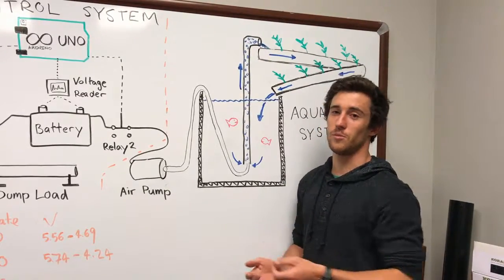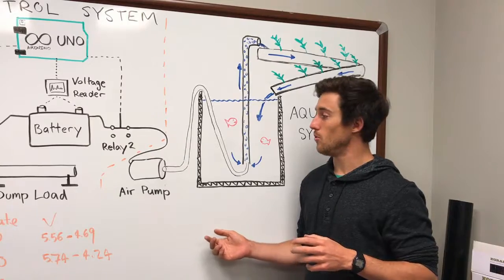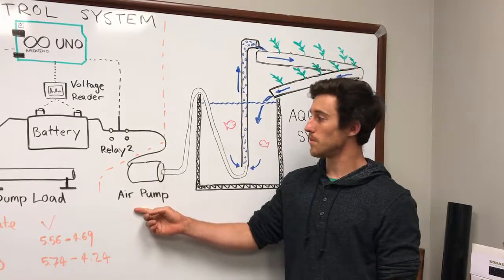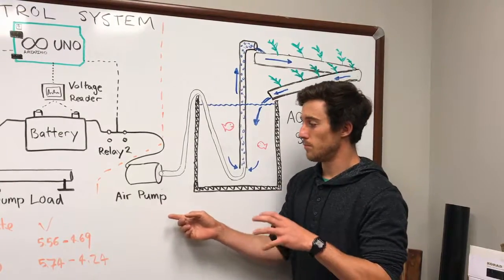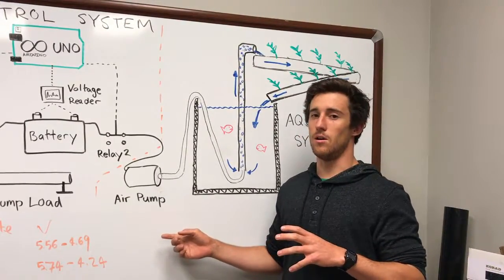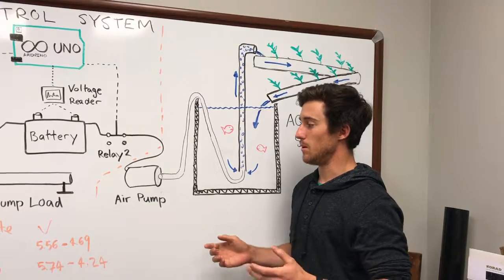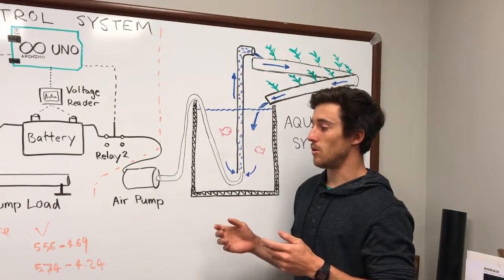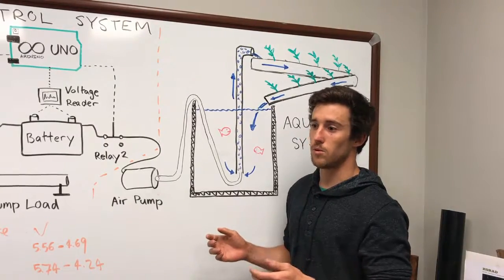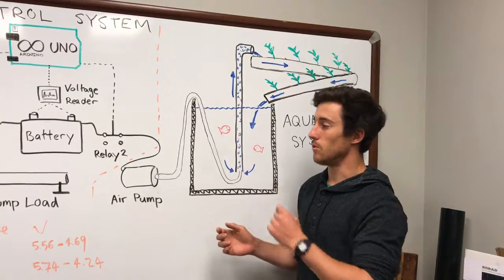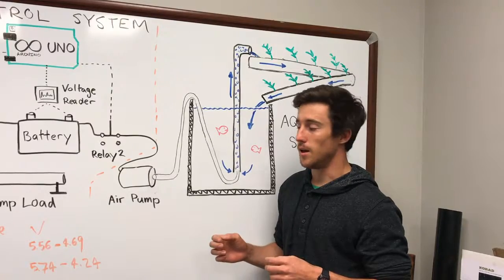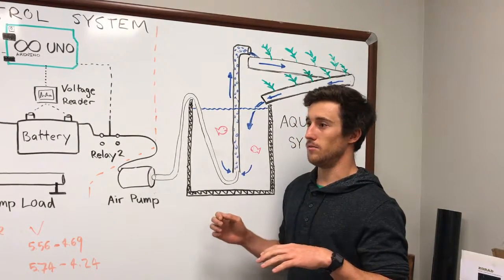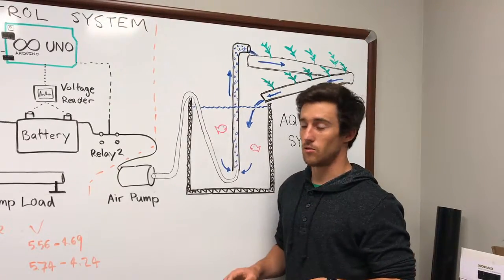The third and final stage of our entire system is the actual aquaponics system, where we use power generated from the wind turbine to power the air pump. We're using an airlift setup so that we're reducing the demand of electricity that we need, because to move fluid using a standard water pump requires a lot more energy versus compressing air and using the power of differences in density to our advantage.